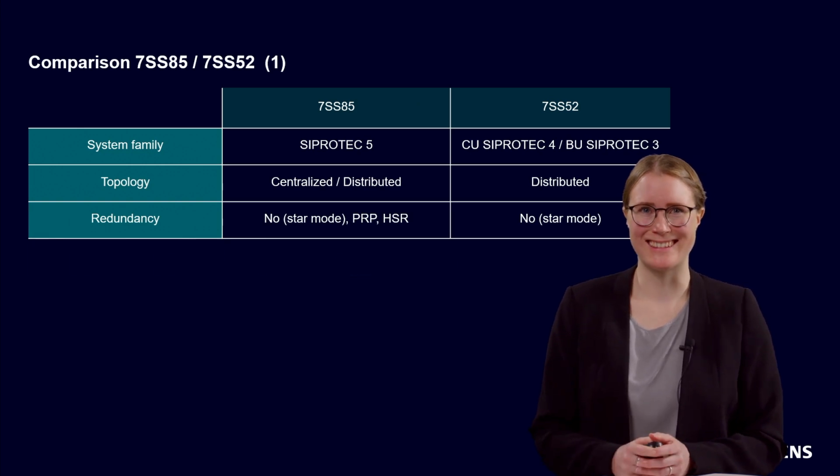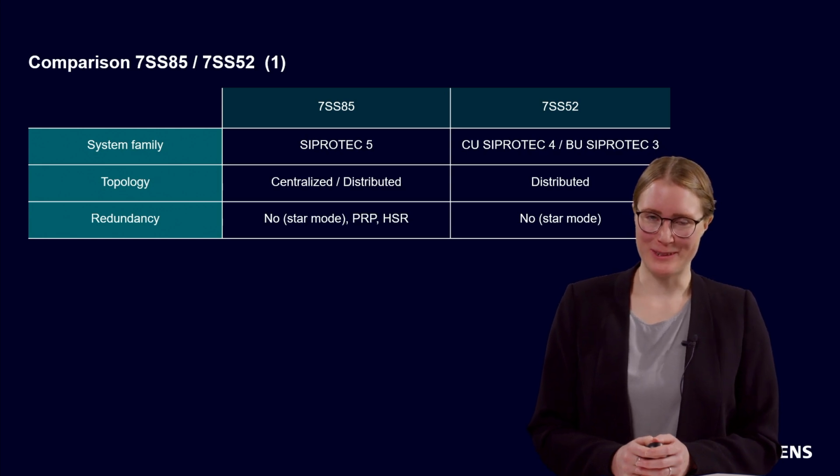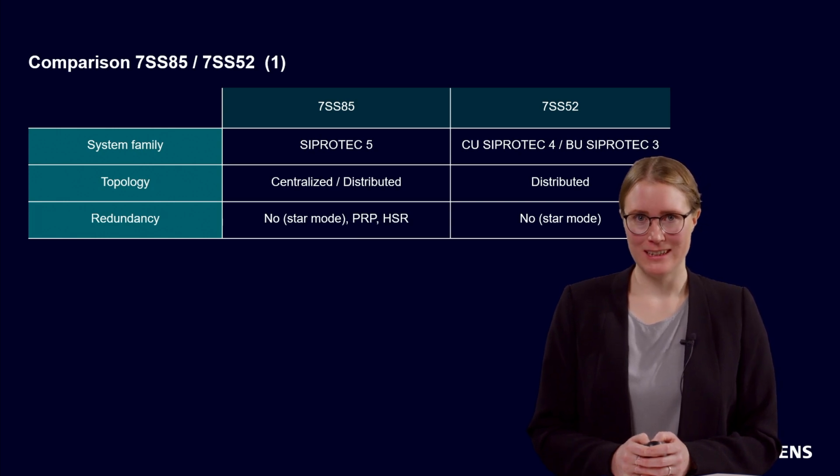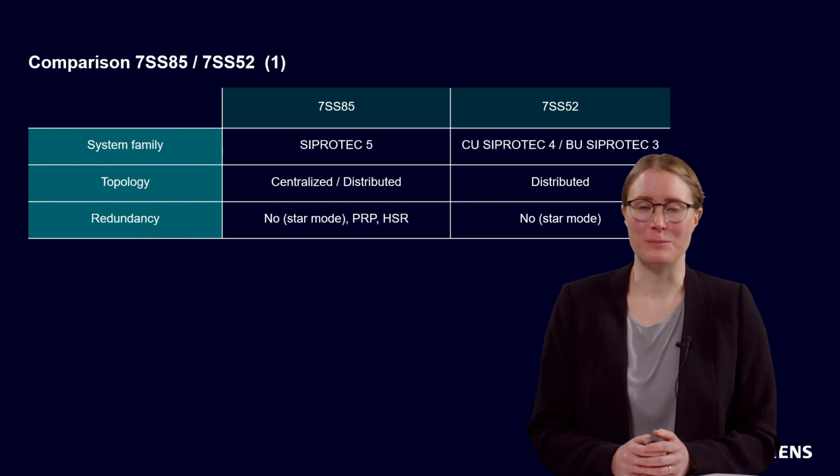The time synchronization is in Sipotec 4 done by the protocol. In Sipotec 5 you can use since version 9.20 the integrated grandmaster clock. No additional equipment is needed in both cases.